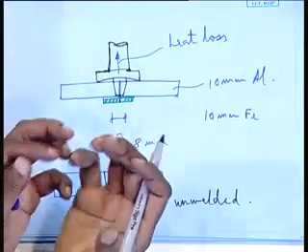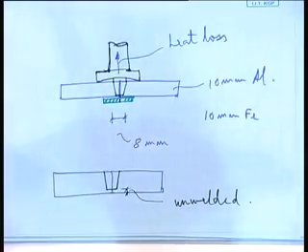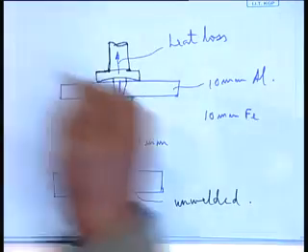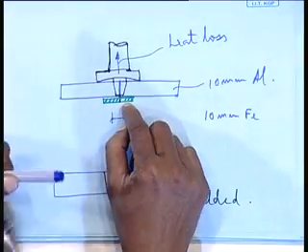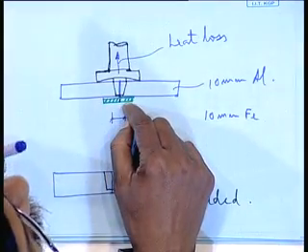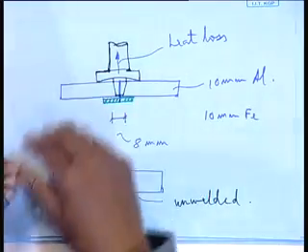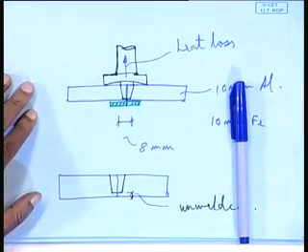That means the backing bar also will take out heat, right. So, that again tells us what the backing bar material should be, and that means it also ought to be of a material which has a lesser thermal conductivity.